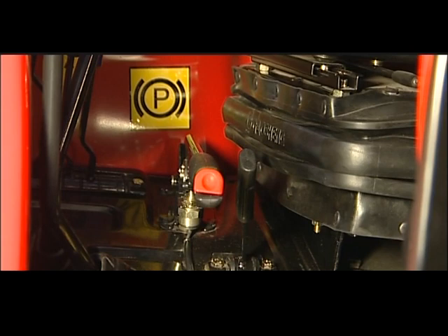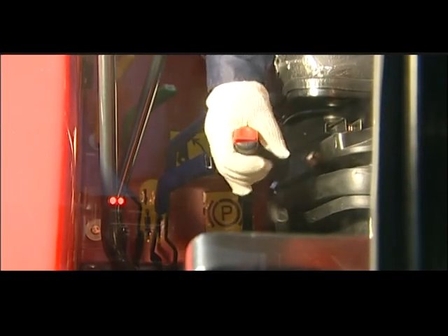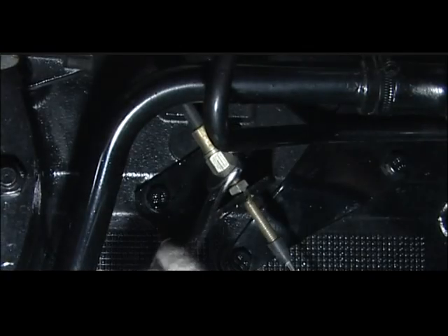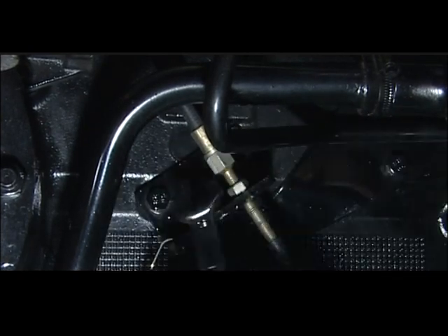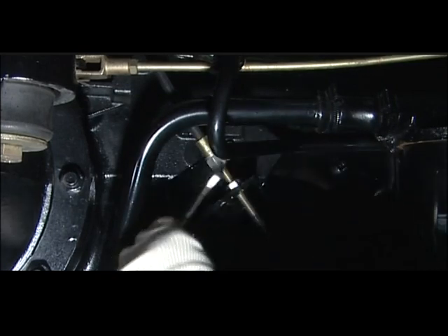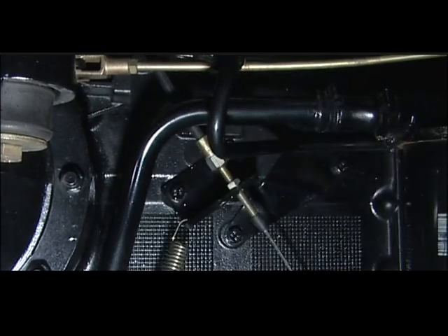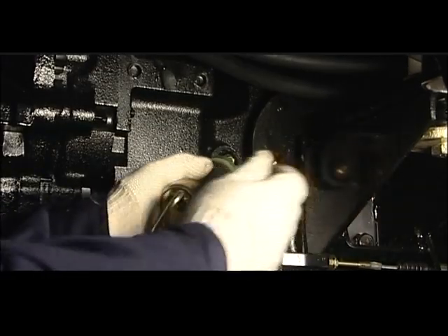Regulation of parking brake. When the free stroke of ratcheted sector panel exceeds 5 ratchets, regulate as the following methods. First, loosen the nut. Turn the connecting lever until the free stroke to sector panel is about 3 to 4 ratchets. Then retighten the nut. Refills with lube grease as the tractor maintenance chart.